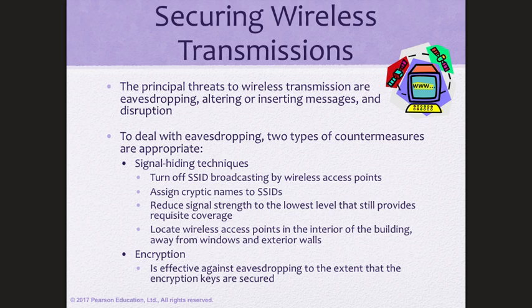Okay, rather than having the 1 watt focused on 1 kilohertz, and it's with a level of 1 watt, right? You spread that across a few megahertz. The total should be 1 again. So this means that if you make it wider, you make the level much lower. Okay? Any user who doesn't know exactly how to gather back that signal into the original band, they will not be able to detect your communication.